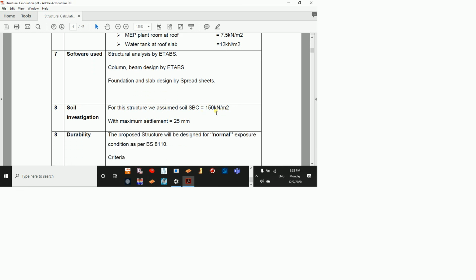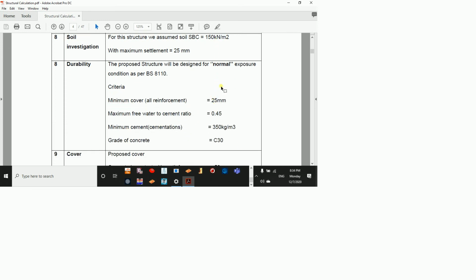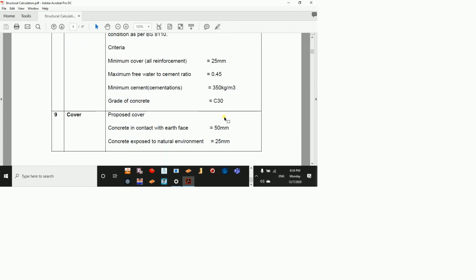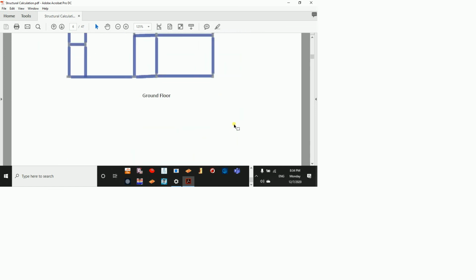Maximum steel bearing capacity, you should get it from the municipality. Okay. So certain things you need to mention. For example, the cover. Now, according to the code, it says the minimum cover is 40, but we regularly use 50. Okay. So a lot of things are very important.